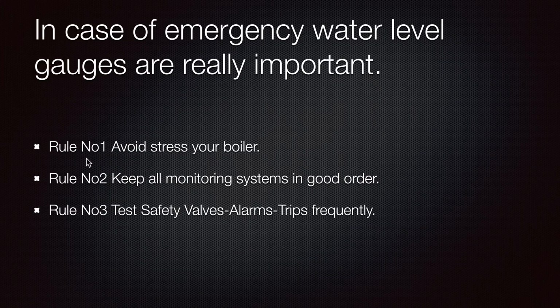If the level gauging system of the boiler has a problem and we cannot identify the proper level of the boiler, because air may have entered the measuring system, we will get a reading which is not appropriate. In that moment, we go directly to the local boiler water level indication, and we see the water level from there.